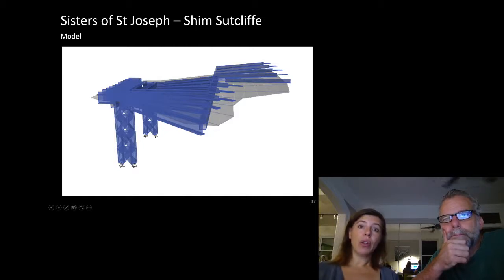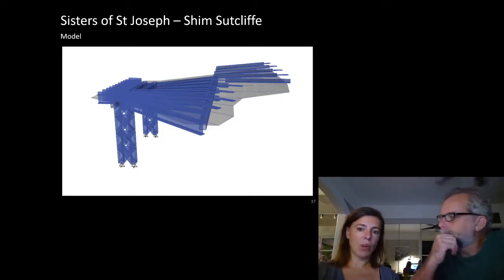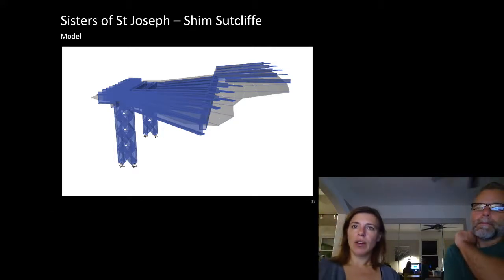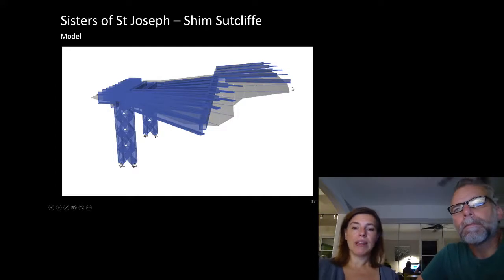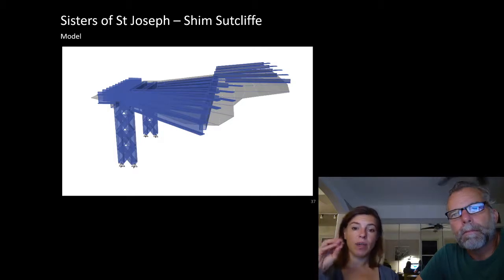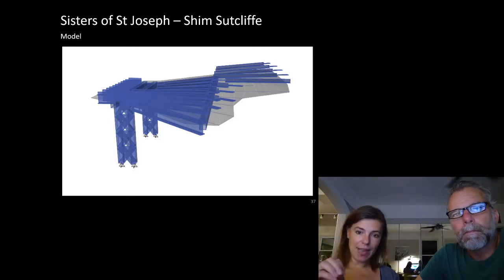I mean, I could do this by hand and do that method of sections because it's not a normal loading diagram from the different standards that I've shown you. So I would have had to do method of sections at like 10 discrete points along its length with changing shape properties along its length to resist those loads. But the modeling software does all of that in absolute seconds.